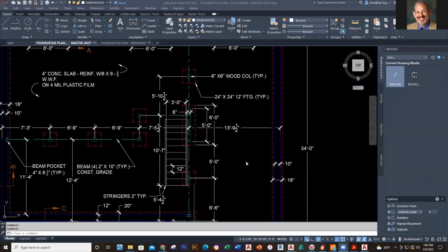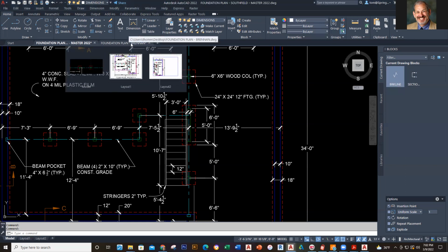Okay, so what I'm going to do here is I had put this off here. Now what I'm going to do is I am going to start to craft these over here. Now over here, you'll notice that I've got the beam. The beam is the cyan dash line, and my columns, you'll notice they're green, and they're right centered on there. So what I'm going to do is I'm just going to offset those to get those in place. Then we'll kind of move on from there. By the way, this needs to be 5 feet 2.5 inches right here. So I'm going to offset that to give myself that. So I'll offset that just to give myself something else to work with.